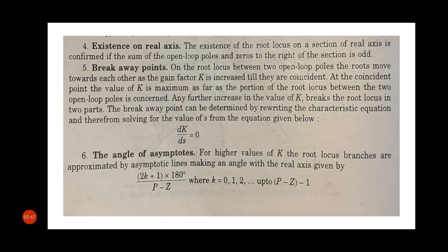The breakaway point can be determined by rewriting the characteristic equation and then solving for the value of s from the equation dk/ds equal to 0.